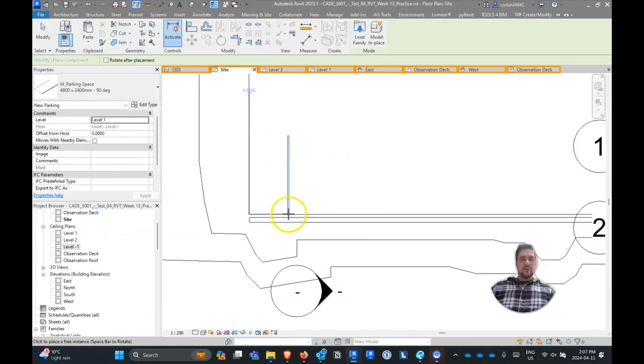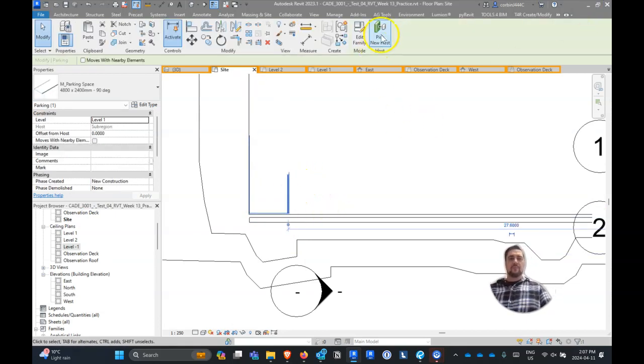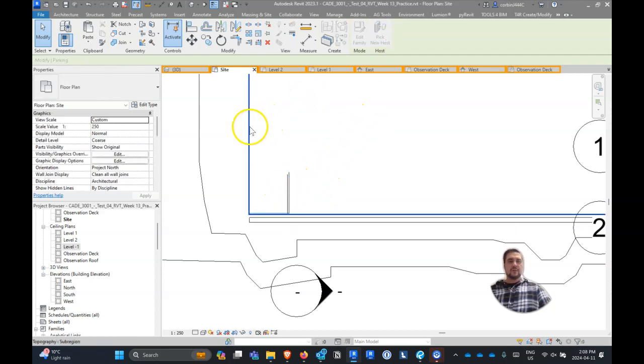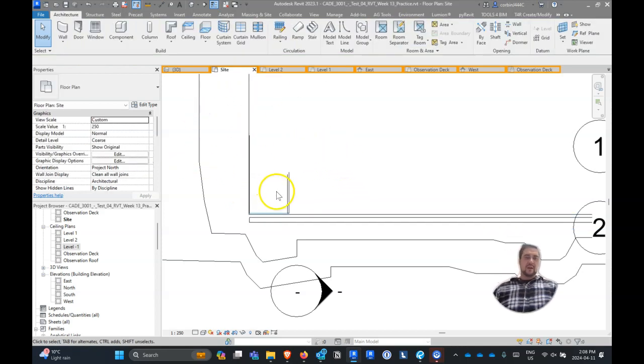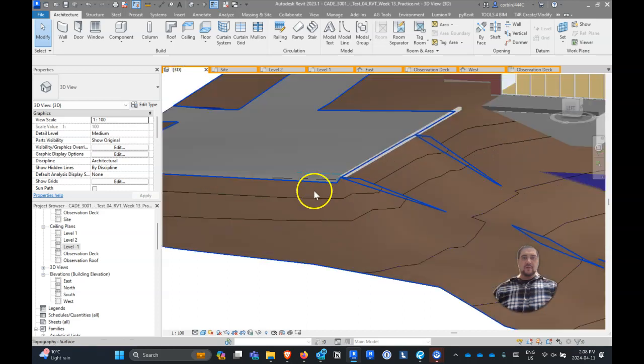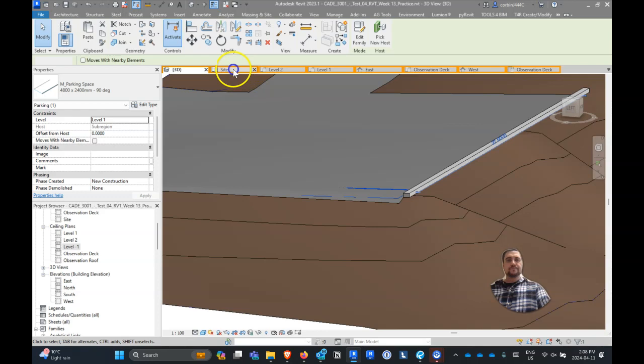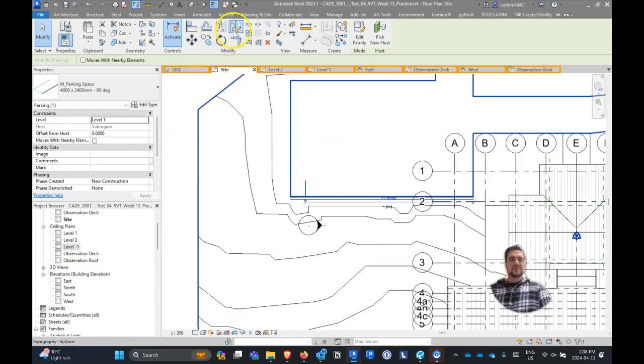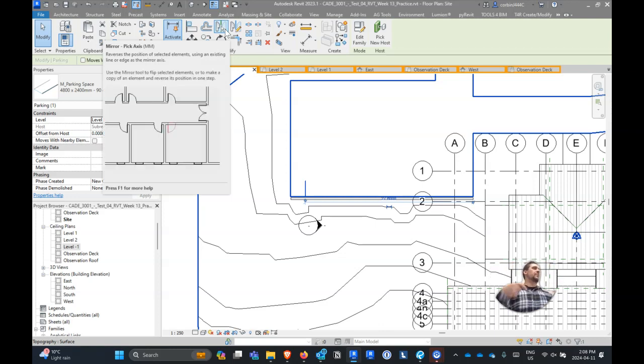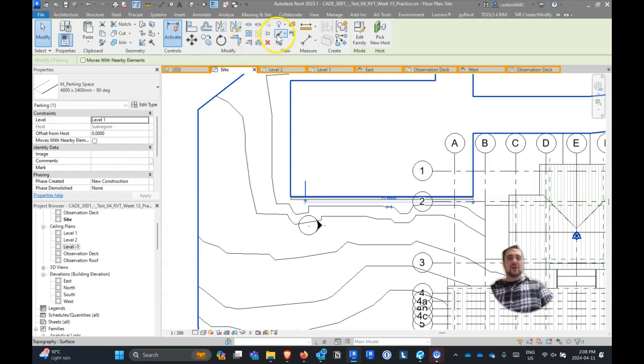here in Revit. What I like to do is add these parking spots, and we can pick host, and picking host will bring them onto that area itself. So it is cutting through the ground, I guess, but it is showing somewhat there. We'll just array this across, and then what I usually do once I do this is adjust that topo subregion to fit the parking spots. So I kind of have it roughly laid out to start, and then we adjust a little bit after.